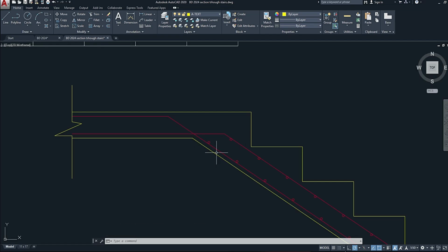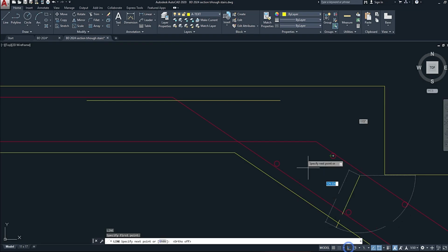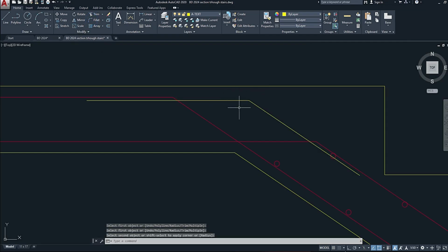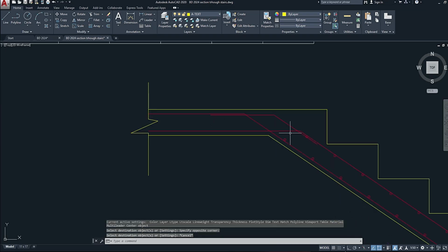What happens to this zero location here? All right. Now, this is my recommendation, is that I'll splice a steel from here, lap a steel from here. It will go across like that. All right. And then it will be the same thing along here as well. Lap a steel, and it will go across. All right. And then that bend there would reinforce this area. All right. So that is my technique and my strategy for reinforcing staircases.